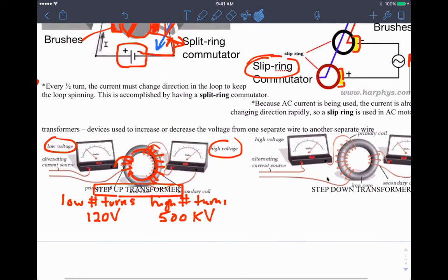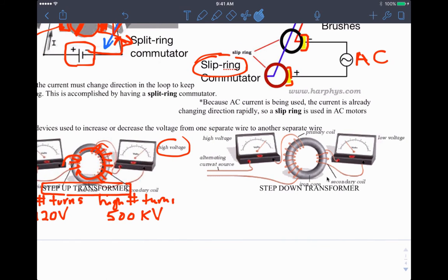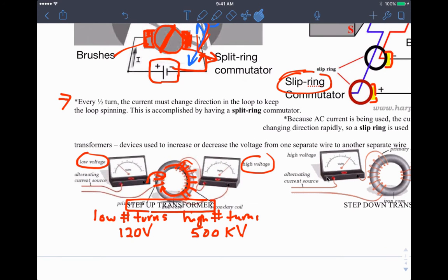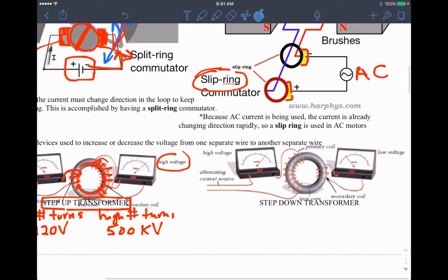So the opposite of a step-up transformer is a step-down transformer. And this is literally what happens after you've done this step up. Basically, when we generate electricity, we tend to generate low voltage, but then using a transformer, we can step it up, and then it's transmitted over the power lines to your house. But you don't want 500 kV or 500 kilovolts of voltage coming into your house. It would destroy all of your electrical devices. They'd all explode, basically, catch on fire. So we safely step that back down, and we do just the reverse. So it's a really unique setup.